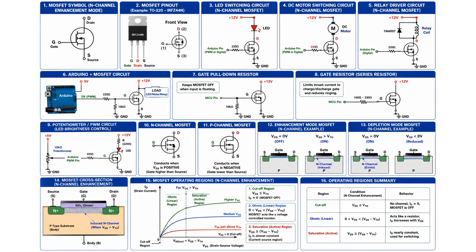However, a slowly varying analog voltage often holds the MOSFET in its linear region, where the voltage drop across the device is significant and power dissipation rises. The MOSFET can become quite hot. For efficient LED dimming, PWM is almost always the better choice. If you do experiment with a potentiometer, monitor the temperature carefully and keep the current modest.